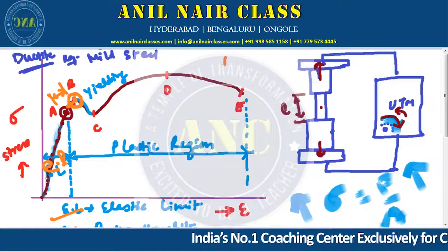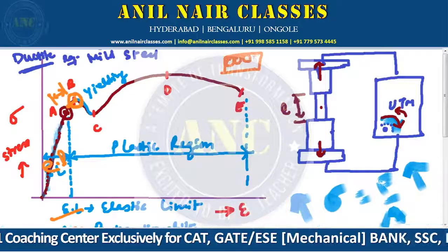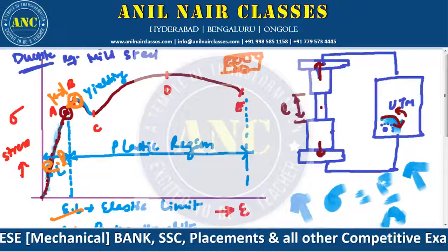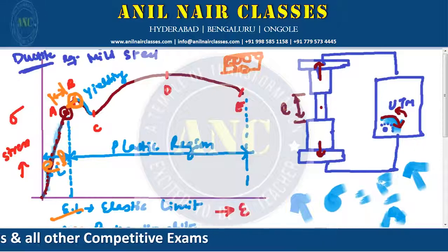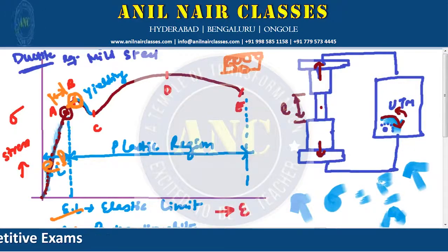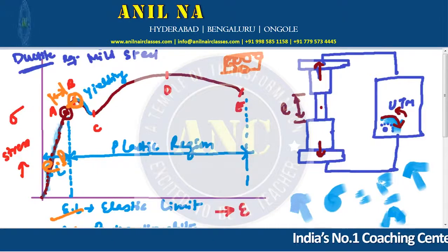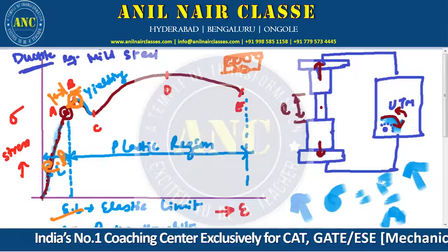That is the dislocation. You know, we have bodies. This body will be having atoms, correct or not? So what happens? This atom, say it shifts here. So this dislocation only happens at B. Because of this dislocation only there is a change in the periphery of the body. So the dislocation starts at B. So we can say the maximum load at which the deformation starts is called the higher yield point.